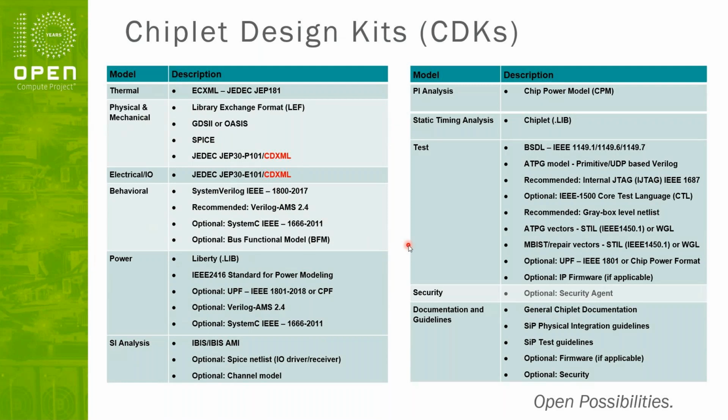These chiplets, typically they will be provided as known good die, but known good die, I like to call it known pretty good die, because they're tested at wafer sort, which may not be representative of once it's put into a package. So typically for package parts, you're always going to run a final test. So we believe it's important to provide the test patterns, so the system integrators have the ability to test those individual components, the internal structures of the device as well. And of course, advanced DFT tools are available to do all of your chip level and die-to-die testing through some of these standards.